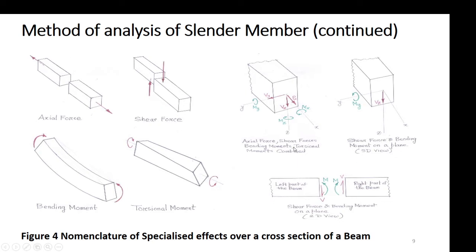And in the beam, we will not consider the twisting moment. Also, for simplicity, it's a 2D beam, 2D effect. So the off-plane shear Vy we will also think of as absent. A beam is usually not predominantly subjected to axial forces, so we will neglect that. Also Mz, the moment about the z-axis, we can neglect, and we can say a beam in 2 dimensions will be predominantly subjected to the moment My and Vz.